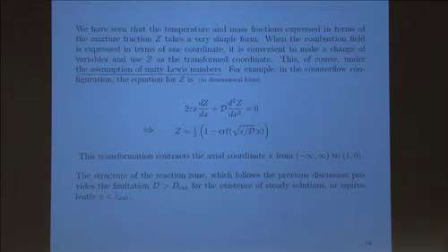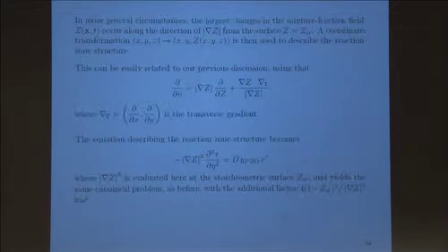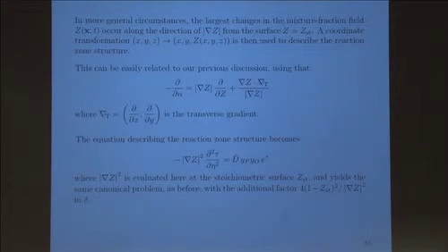In other words, Z is nothing more than either expanding or compressing the coordinate. So in this case, it's like taking the infinite domain from negative infinity to plus infinity for the stagnation point flow and reducing it to the coordinate Z from 1 to 0. So it's like a transformation. But in more general problems, that's not necessarily the case, because in a multidimensional problem you have to decide in which direction you are doing this transformation to Z. Normally, you do it in the normal coordinate.